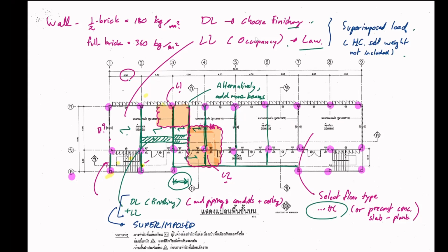On the beam that you add between grid number 3 and number 4, can we extend that to reach the boundary of the corridor so that it helps support the floor? Yes, you can in the real world, but it's going to create a lot of trouble when you're trying to make continuity here, because you need another support here to support this beam. Okay, I see. Let me finish this because your point is good. I say that you may not have to use this one. So let's forget it.